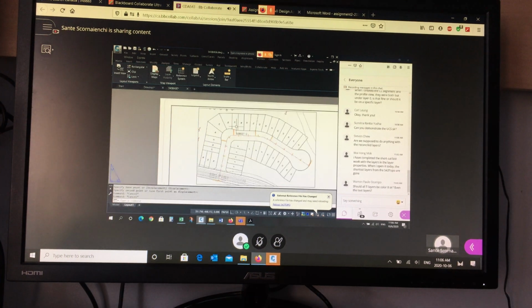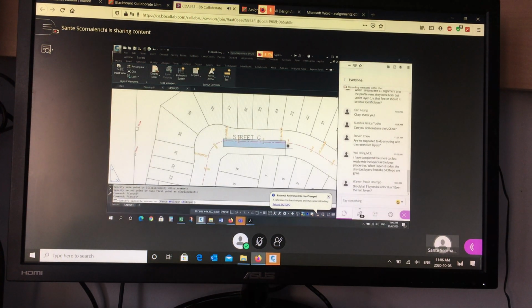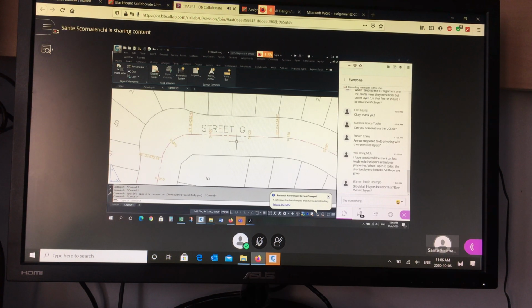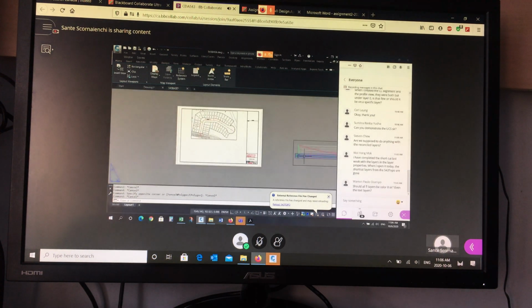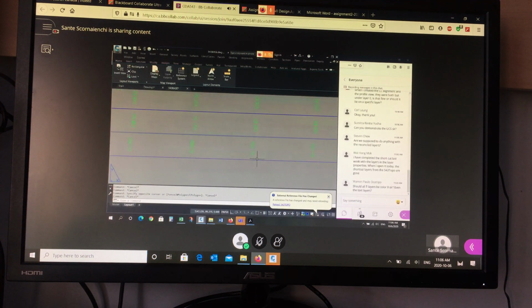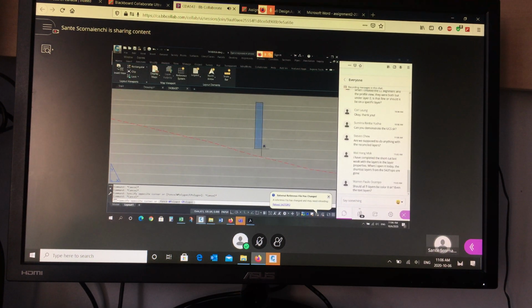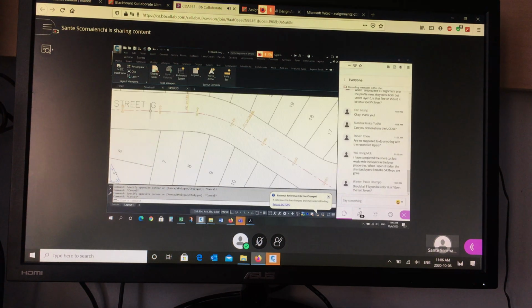So that the stations, this piece from here to here, is horizontal to the view. So station 100 here in the plan should be directly above station 100 in the profile, right? Station 100. So you want this vertical gray line here, this vertical gray line, to be directly below station 100.